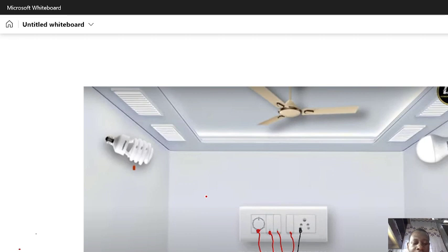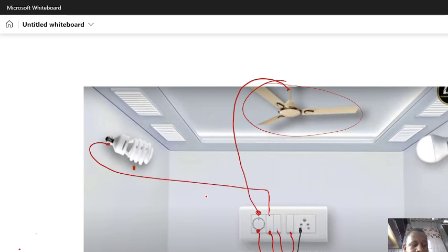This one, 3 different switches. So now this potentiometer or this regulator, we already discussed in the first video of our practice. The regulator controls the speed of our fan. So now this regulator will go directly to the positive terminal of our fan from here. Now I have this also. This one is our switch. I can connect this switch to this lamp, and another switch from here is going to be connected to the positive terminal of this lamp.